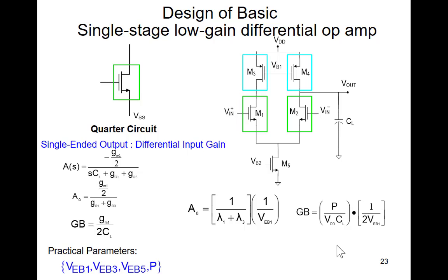Make sense? I can't emphasize strongly enough how you would have a difficult time making those observations if you were in the natural parameter domain. So how you look at the problem can make a big difference in how hard the problem will be to design. You decide to use this architecture. Your boss comes in and says, you can't let VX's bias be any smaller than this, and I want the gain above a certain level. You look at this equation, you can say, yep, I'll do it, or it's not going to happen. Make sense?